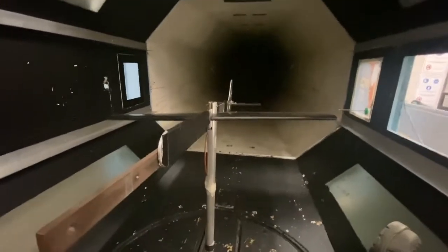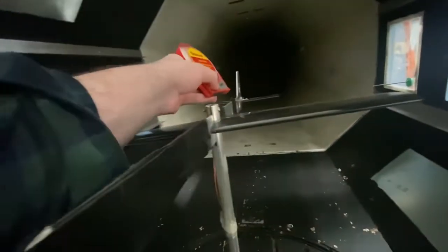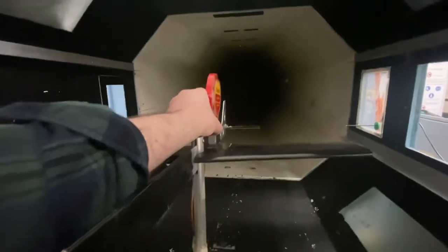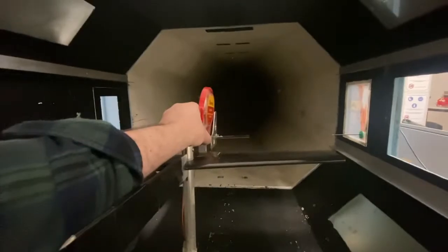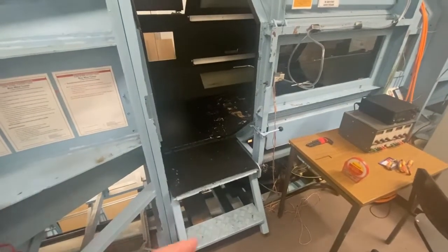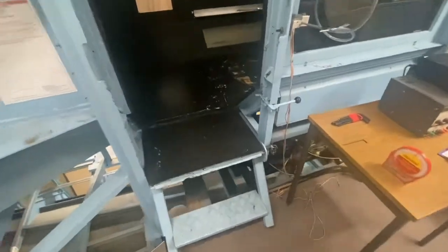Once you have selected an angle and the bolt is fastened, you need to take this angle meter and place it somewhere flat, such as the top of the fuselage. Your lab partner should be outside, looking in through the window to assist you in reading the angle. Further adjustments may need to be made. Once you have set your angle of attack, we need to set the wind tunnel up for operation. Begin with closing the doors.